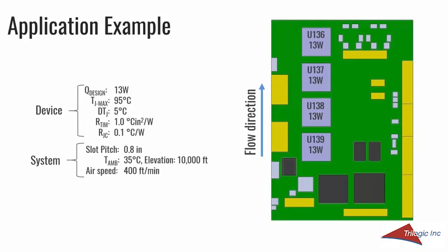It doesn't really require anything too exotic for interface. But with monolithic heat sinks, typically you're going to be required to have an interface material that can compensate for the tolerance in the component heights and make sure that this heat sink seats properly on all the components. So I think an interface material resistance of 1 is probably a reasonable assumption.